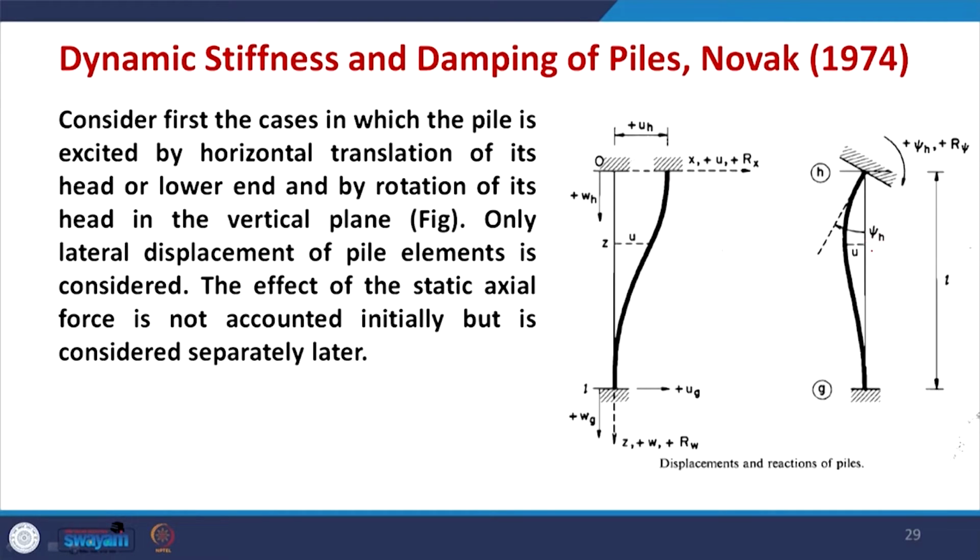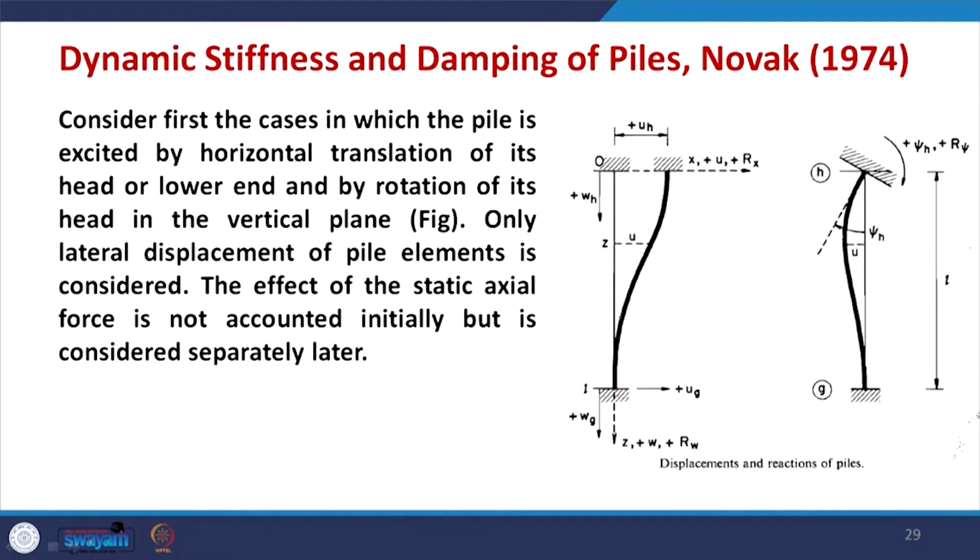So, when the pile is subjected to horizontal mode of vibration, first of all this is an end bearing pile. So, this is fixed here, and let us say we have considered that pile head is also fixed against the rotation in this case, and it can move in translation. So, when you apply the horizontal displacement or load, this is the horizontal displacement given by some earthquake, or whatever. So, this point moves from here to here, but this remains fixed, and the u will vary along the depth. Naturally, the value of u is maximum at the ground, and minimum, 0, at the base.